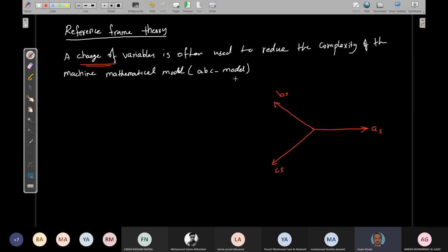When we have a single coil, that depends on the geometry of the machine, salient or non-salient. Even for the non-salient, it will generate pulsating torque, and the average value of that torque will equal 0. So in order to generate a torque, I need at least two coils.